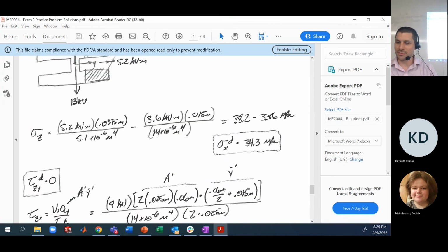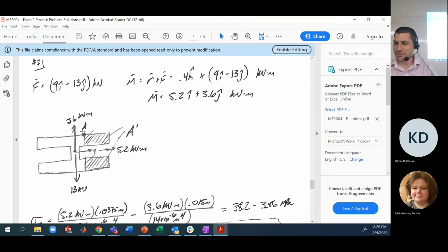Shear stress tells you why. You could convince yourself again that if you're interested in some contribution of shear from the Y direction, this 13 kilonewtons, I can imagine drawing a thickness at this point that contains D, which is perpendicular to this 13 kilonewtons, to define the variable little t. What is the area above that line that I'm currently drawing? 0. So the shear stress contribution from this 13 kilonewtons is going to be 0. That's again because it's on the surface. The outward normal is upward.